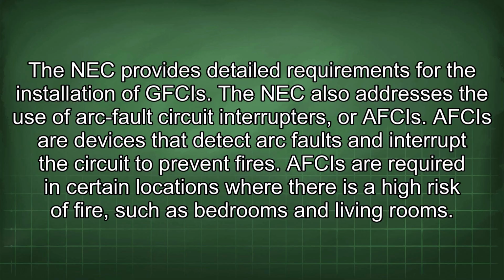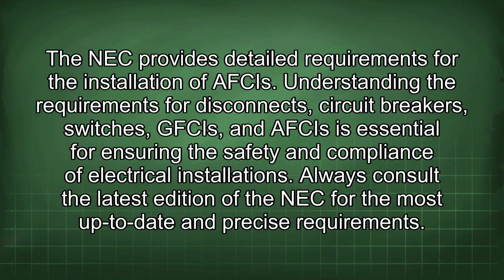The NEC also addresses the use of arc fault circuit interrupters, or AFCIs. AFCIs are devices that detect arc faults and interrupt the circuit to prevent fires. AFCIs are required in certain locations where there is a high risk of fire, such as bedrooms and living rooms. The NEC provides detailed requirements for the installation of AFCIs.